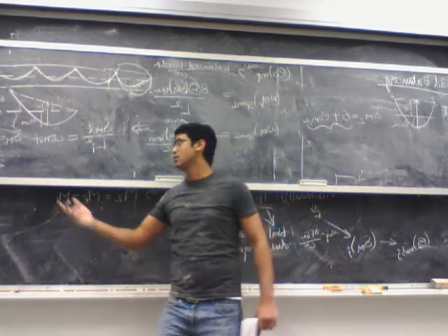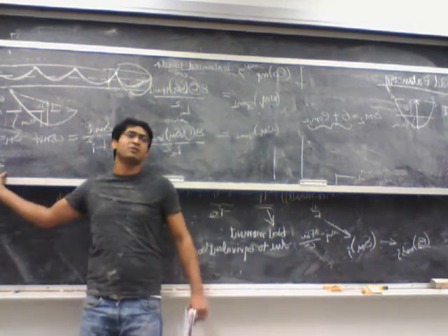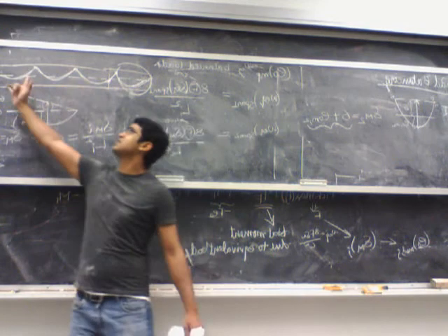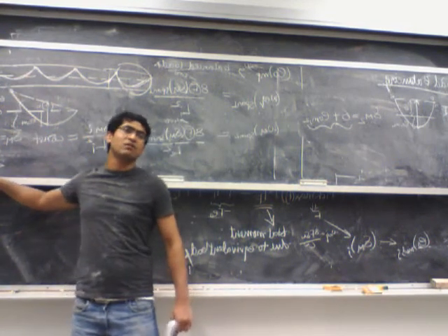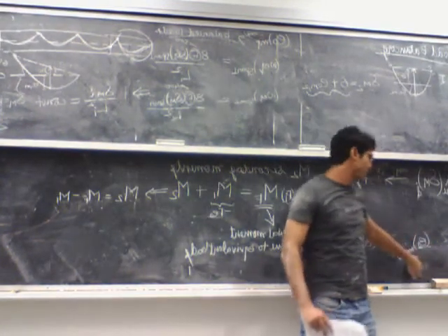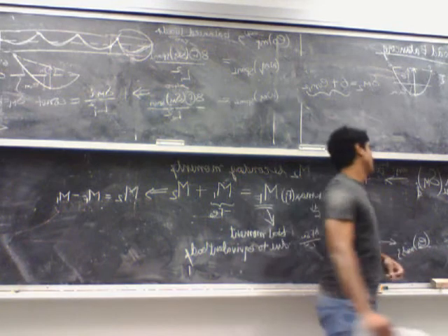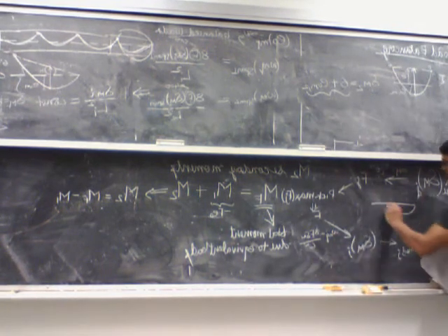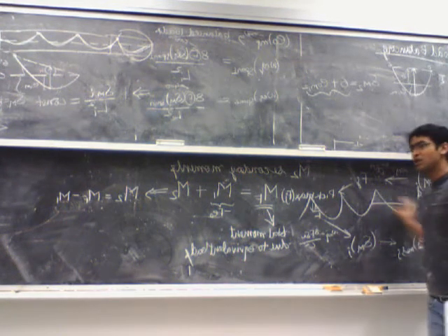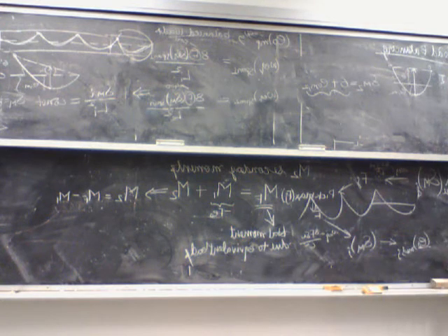Now, how much less? You can actually start with 85% or 90%. You assume that this E naught at the mid span for span 1 and, let's say, the last span, is only 90% of the maximum allowable. Based on that, you do all these calculations and finally come up with the final value for the E naught. And then when you define the final tendon profile, you make sure that the maximum E naught anywhere is still less than E naught MP. Because right now you just assumed a value at this point, the mid span, but it might actually drop down and increase further.